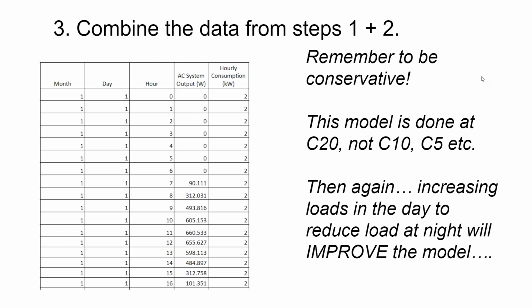When you're draining the battery by 50%, that means you're draining it over 2 hours, and that is much more typical of how you would use a commercial battery for peak demand management. Whereas a C20 rate would be like discharging a 100 kilowatt hour battery bank at 2 or 3 kilowatt hours. That's like discharging it by 2 or 3%.